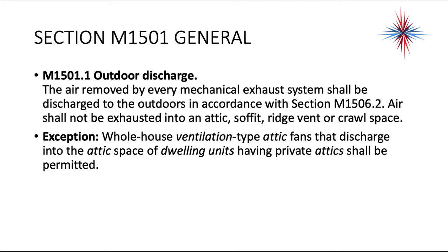So what it's basically saying is that every exhaust fan in the house, bathroom exhaust fans, kitchen exhaust fans, basement exhaust fans, needs to be exhausted outside. You're not allowed to exhaust just to the attic. You're not allowed to exhaust to the soffit, which is the area around the eaves. You're not allowed to exhaust to a ridge vent or a crawl space.